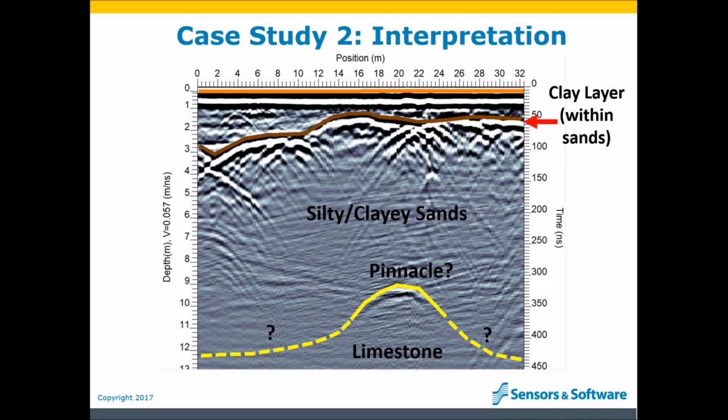I will say that there are airwaves in this data. I think some of these higher frequency sloping events are airwaves. The discussion of clearer, better imaged airwaves in the highly stacked data leads to another concept that is important to clarify so there is no confusion. Stacking GPR traces improves GPR data in terms of signal quality and depth of penetration only if the background RF noise is random.